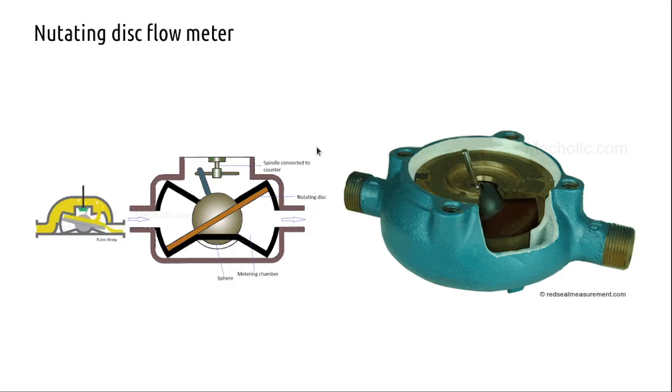So this chamber, we are causing this disk movement, and you are correlating this disk movement to the fluid flow. A particular amount of fluid is there in this. We very specifically know how much it is, and it is precisely machined. It is going to create a rotation, and you are correlating this rotation to, say, liters, kiloliters per hour or gallons per hour. You will calibrate it.